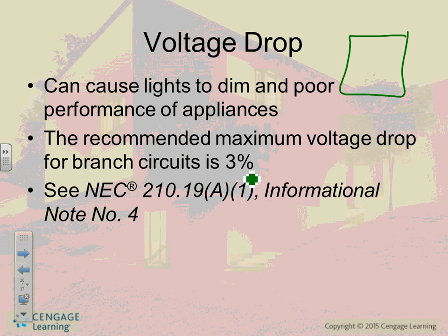Based on UL listing, guys, typically a piece of equipment, an AC, when it's rated for 230 volt, single phase, it says on that, this means it's UL listed typically plus or minus 10%. So you can go 10% higher and the equipment will not burn, and 10% lower and the equipment will not burn. That will allow the utilities like yourselves to up the voltage, lower the voltage, fluctuate the voltage, because the voltage is not constant, guys. Every time you turn something on, it dips. Every time you turn something off, it goes up and down, within a limit of what? 10%. If it fluctuates more than 10% up and down, it burns the equipment.